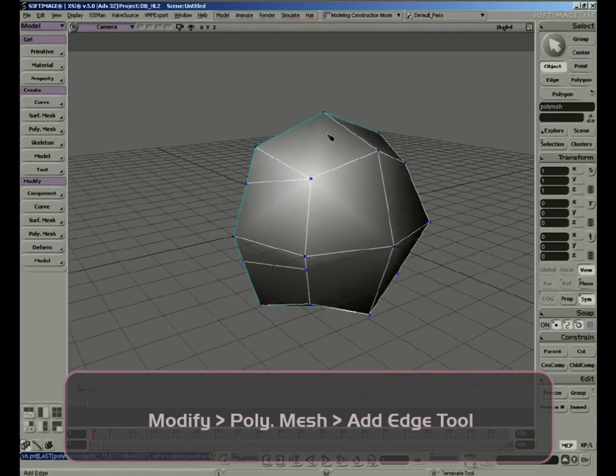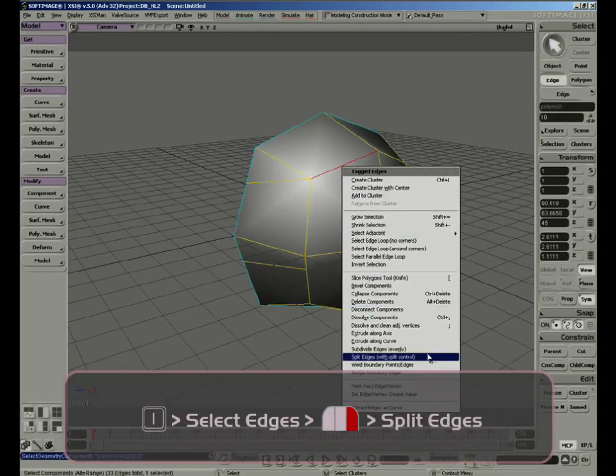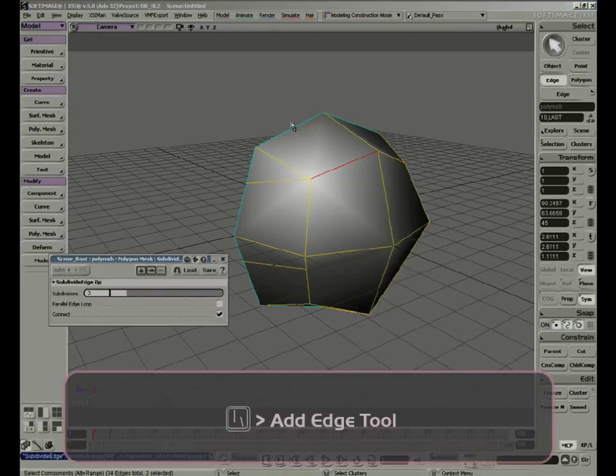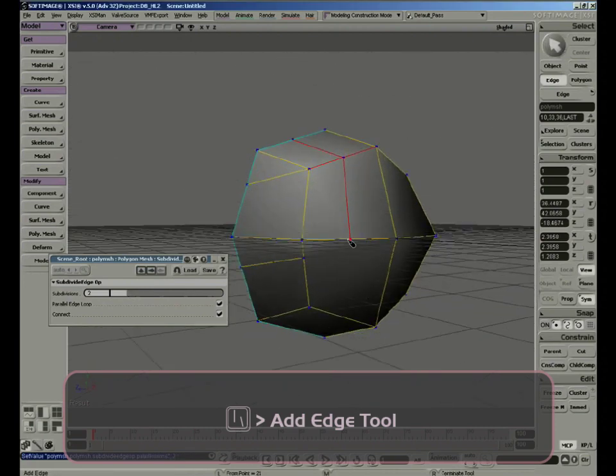We can select an edge and subdivide it with split control, or evenly. Evenly would subdivide the edge by its center. And we can select here our number of subdivisions. Just 1 and 1. Connect from here to here.